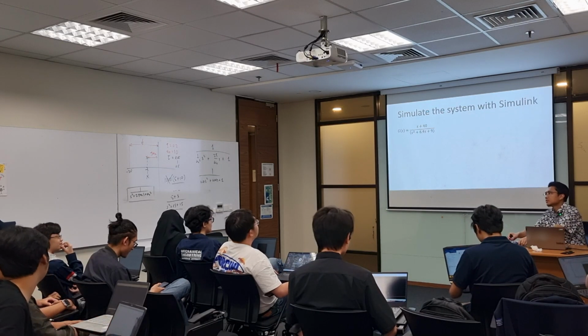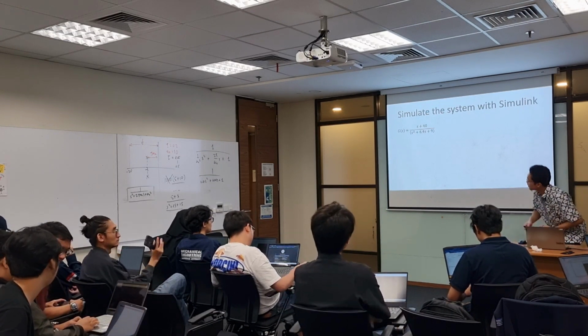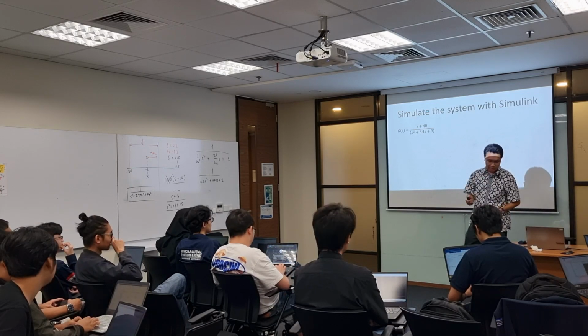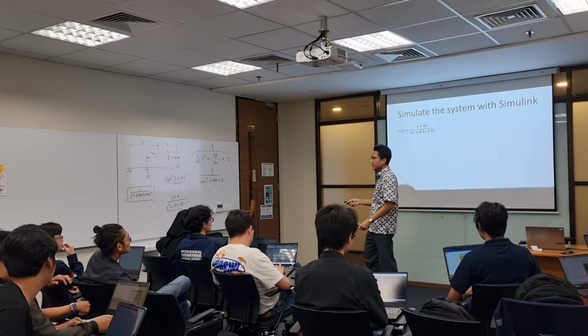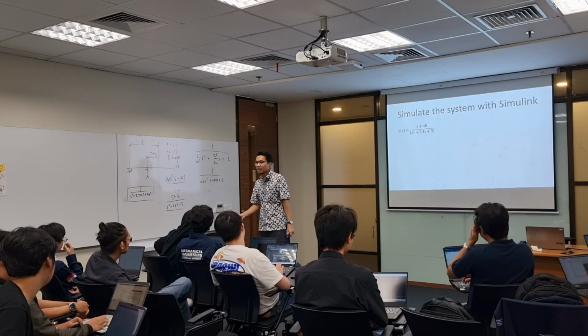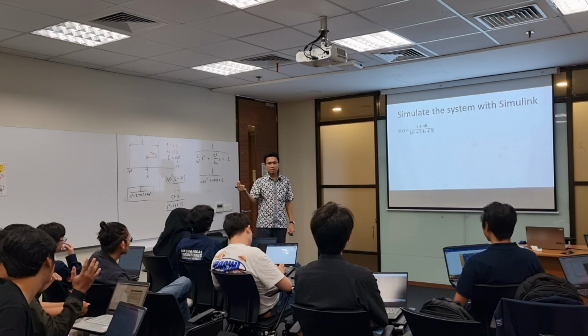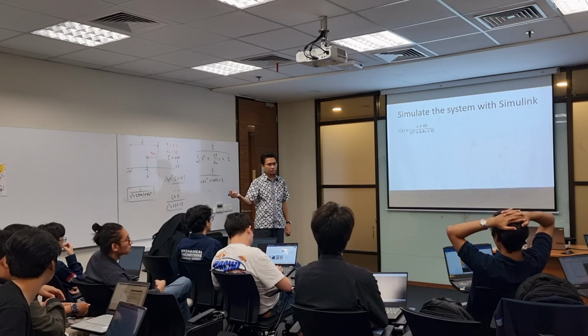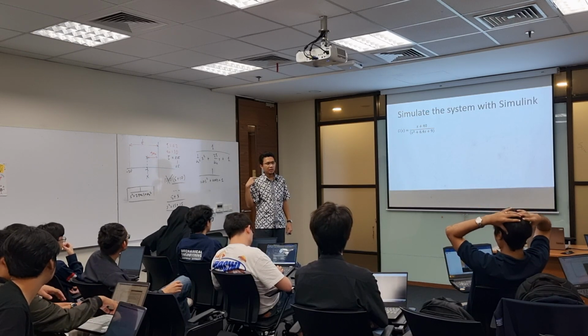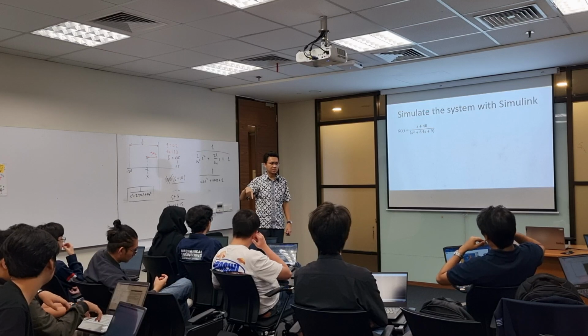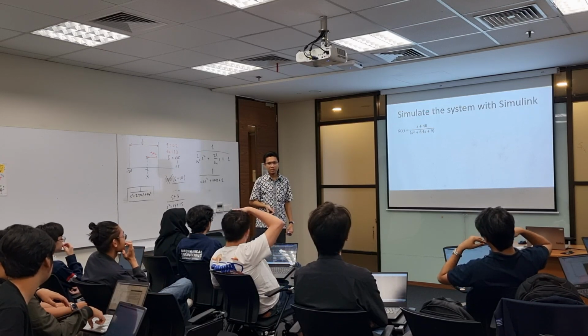Okay. So just now it was a very extreme case because the original system has zeta of 0.8, yeah, very large damping ratio. But then because we move the extra zero close to the origin, the system oscillates. It has overshoot. Okay, extreme case.